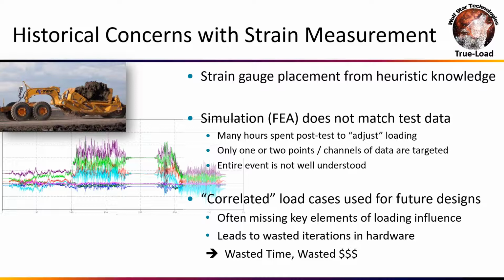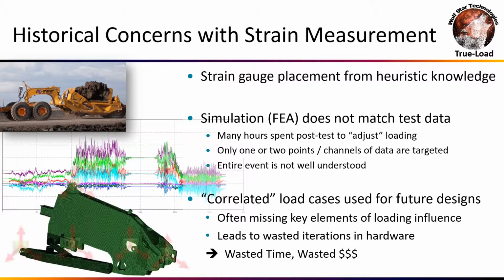So typically what will happen is you'll concentrate on one or two channels of data at one or two points in time, and you'll work for days, if not weeks, to try to get a load case that correlates just qualitatively, not even quantitatively, just qualitatively. You say, yes, that's my load case I'm going to use for redesign, and then you start your redesign process. And then the next time you get back to the field with your next iteration of prototypes, you find that you might have the same problem or maybe even new problems, and you repeat the cycle.